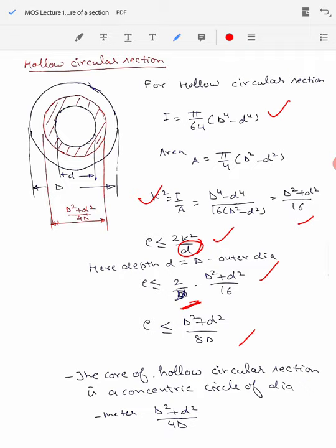The simple reason to increase the diameter is to move their point of eccentricity within the core of the section. Earlier, these concrete pillars were developing cracks on their edges, and the simple reason was that the load was being applied eccentrically, which was causing tensile stresses to be produced. As the concrete could not withstand the tensile stresses, cracks were appearing there.